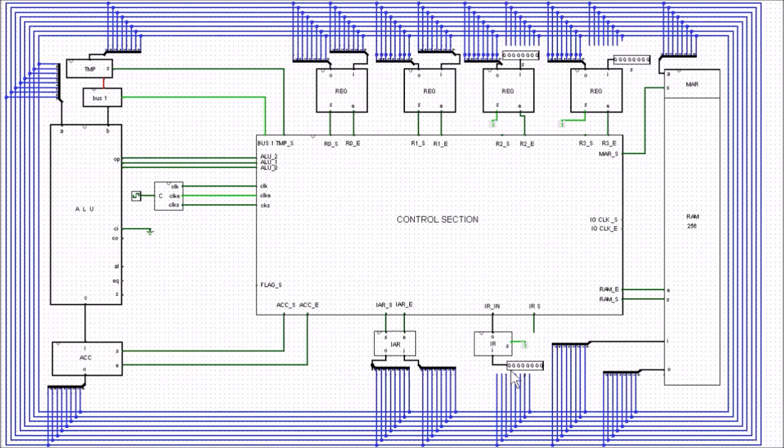So we're going to physically put in our ALU instruction. Our ALU instruction is going to be 1 for the most significant bit. When the most significant bit is high, we know we're in an ALU instruction. The next 3 bits refer to the function that we choose within the ALU. So 000 is the add function.